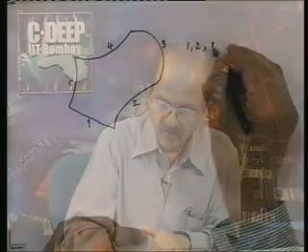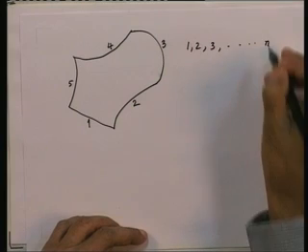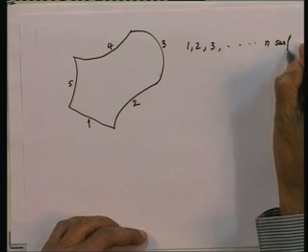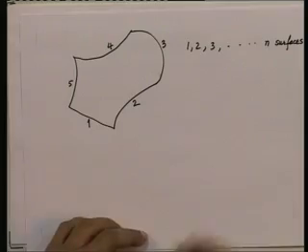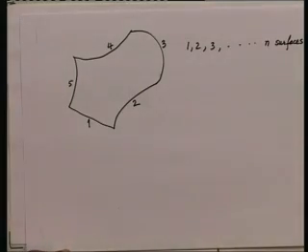it does not matter which. Now, if these n surfaces 1, 2, 3 up to n make up an enclosure, then it follows that all the radiation emitted from any one surface, say surface 1, has to go to all the other surfaces, that is surface 2, 3, 4 etc. up to n, and to the surface 1 itself if F1 to 1 is non-zero.